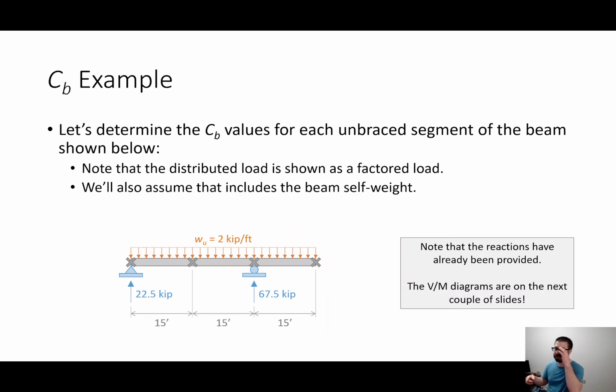Now, a couple things. I have given you the reactions and I've given you the shear and moment diagrams on some later slides. But another thing worth mentioning is that this is a factored load. It's not a dead load and a live load. I've gone ahead and factored everything, so all the loads are factored and we can use them directly.